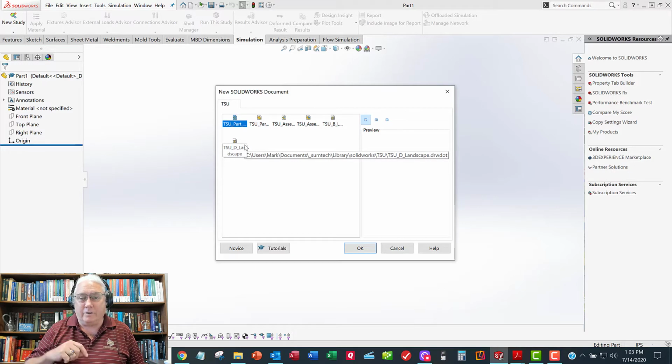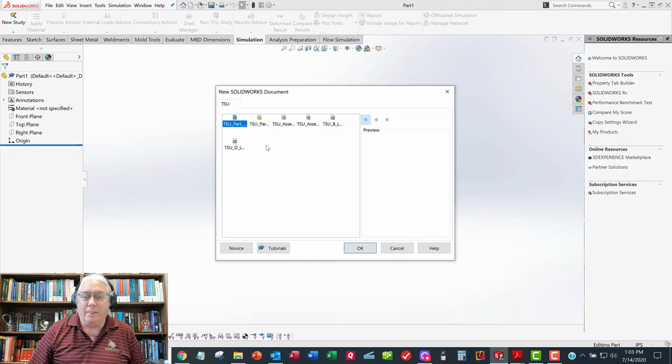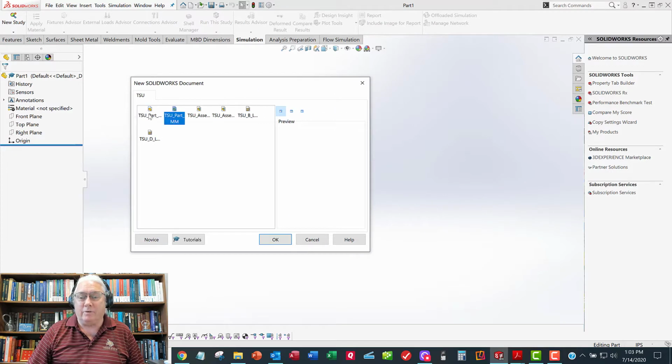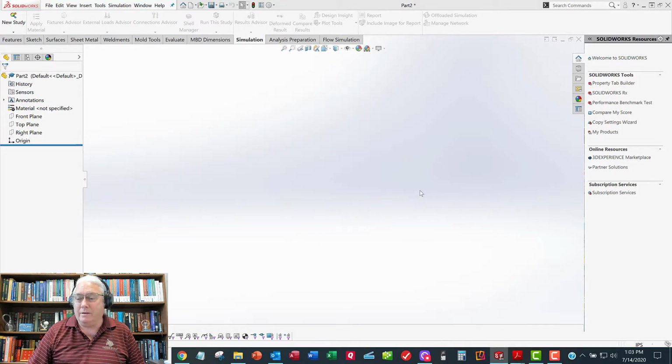We're going to have a sketch of the path that the waveguide follows, and a second sketch of the shape of the waveguide, the rectangular shape. We'll use both of those to create a part model, whereas most extrusions and revolves require 1 sketch. This particular feature requires 2 sketches, one for the path and one for the shape.